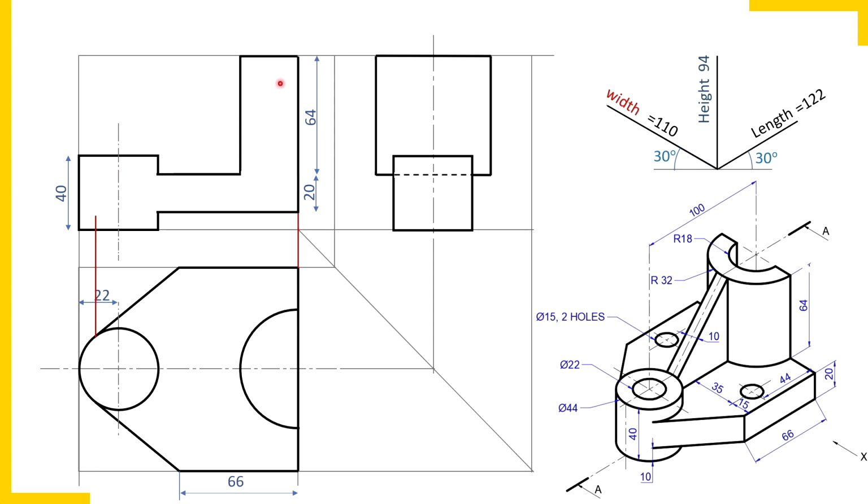Remember, when two portions, this plate here and this semi-cylinder, get cut by a cutting plane, the boundary between the two portions separating the surfaces of the two portions is to be erased. Check here, this is the semi-cylinder and this is the plate. This is the surface of the semi-cylinder here and this is the surface of the base plate.